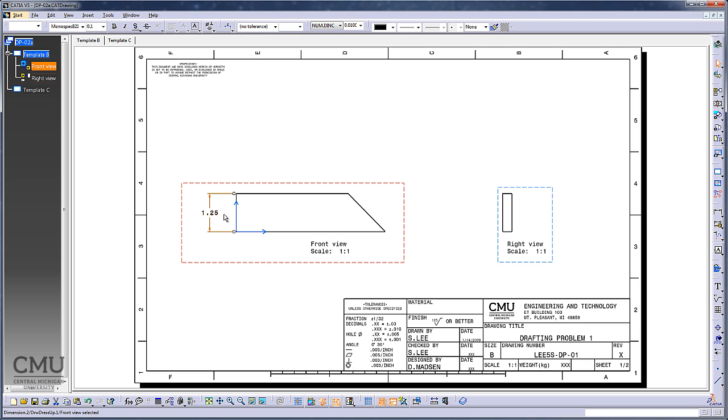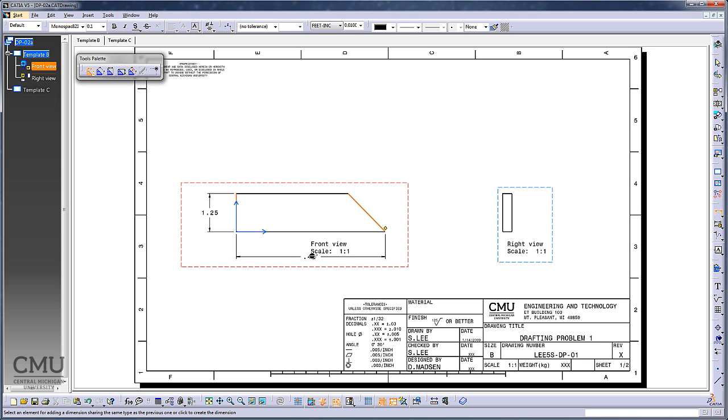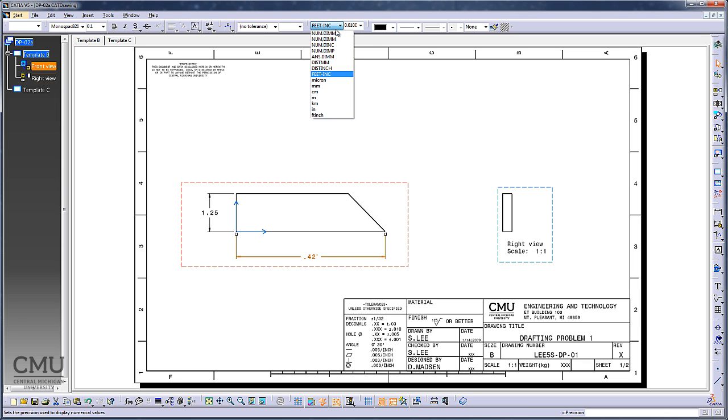If you want to control the number of decimal places, that is right here. So instead of 2 digits, you can go to 3 digits or even more as well. But according to the book, I need 2 digits. There we go. And I need a 5. So I need this one from here to there. Okay, let me take this out. I could just delete it. Then again, I need to make it numeric, dimension in inch, 2 digits.